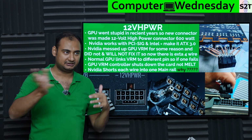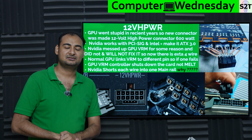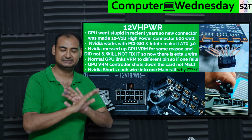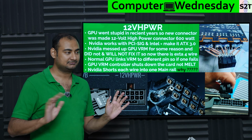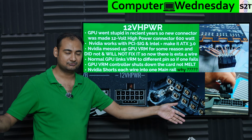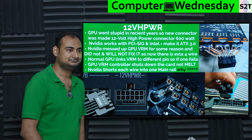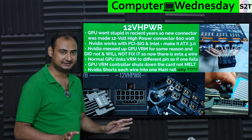The VRM turns on, it waits for a signal from all the phases. It's like, whoa. 2 of my phases are not behaving properly. Shut down the GPU before it boots up. This will happen in microseconds. It's like, bro, I tried to turn it on, nothing happened, because again, I'm supposed to get voltage from all my phases, I'm not getting it, shut down the GPU. The end. No fire hazard, no melting hazard, nothing.